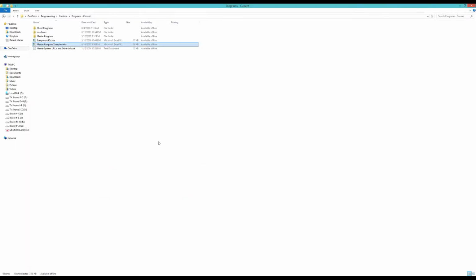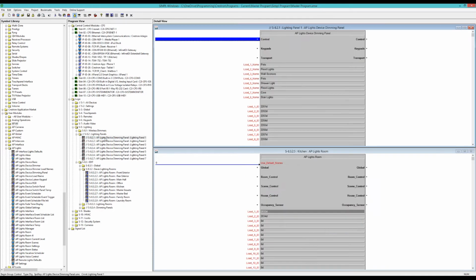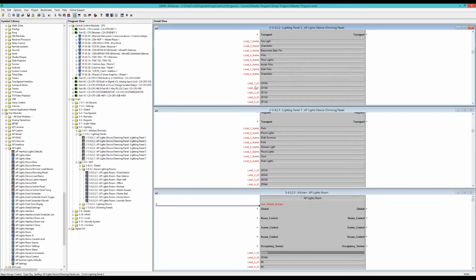And for the dimming modules, I just kept it all sequential. So if you look here, it's 2201 and up, 2201 or 2209 and up, and so on sequentially. You'll notice that I did 2000 and 2100 for the dimmers and switch loads, and then 2200 and up for the dimming modules, mainly because I've done a few houses where both exist when they add lights after the fact and so on, so no point occupying the same space with those identities.